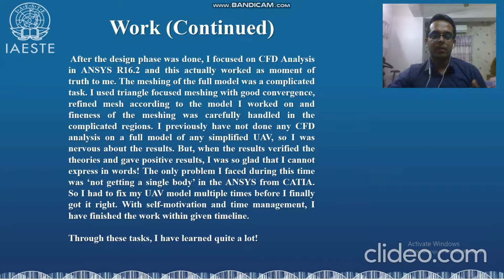After the analysis was done, I saw the results actually verified the theories and gave positive results. So I was so glad that I cannot express it in words. The only problem I faced during this time, though, was not getting a single body in ANSYS from CATIA, because when I transferred the CATIA IGS or IGES file into ANSYS, it was not taken as a single body.